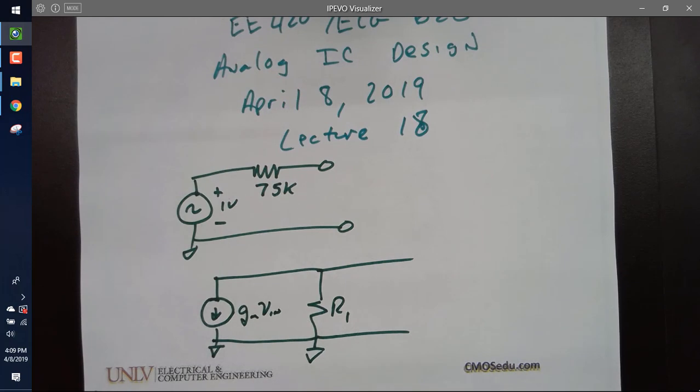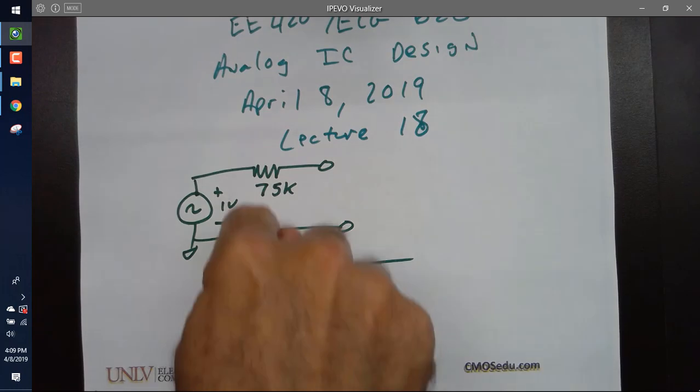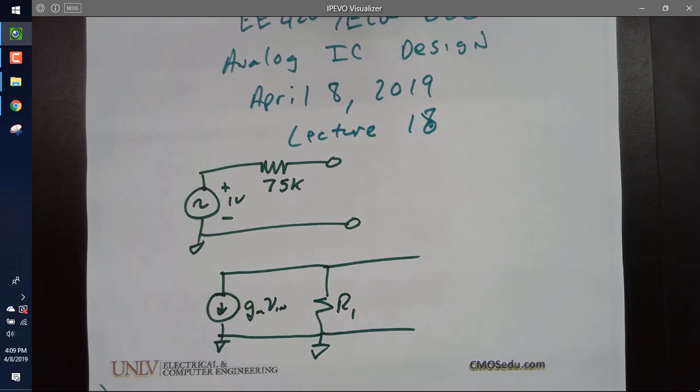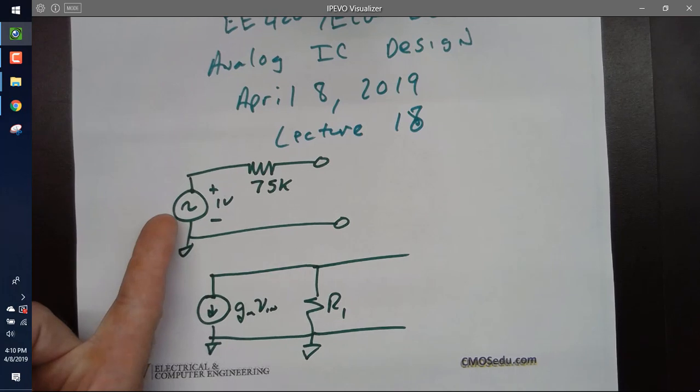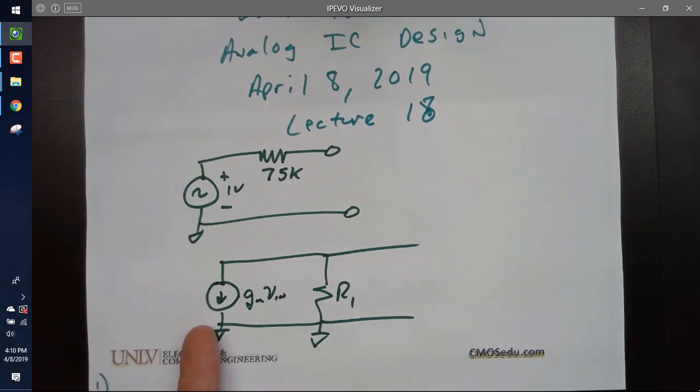What is the R1? Well, let me ask this, even easier. When you're determining the Norton equivalent from the Thevenin circuit, tell me from your instruction, how do you go from here to here? Simple, simple. You're explaining it to someone in circuits 1. There's 2 ways of doing it. One, when you calculate the equivalent resistances, you short out all of the voltage sources and you open the current source.